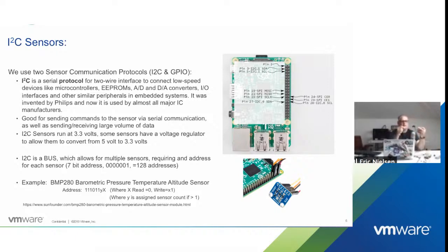This is my sensor. On the back of these sensors, it will usually say power or 3.3 V. It'll also say GND for ground. So I just have to look at those pins and say, okay, there's VCC, there is ground, and there is your data. So I just want to hook my data. I usually use the yellow line for the data line. I use my black for my ground and red for voltage, VCC.